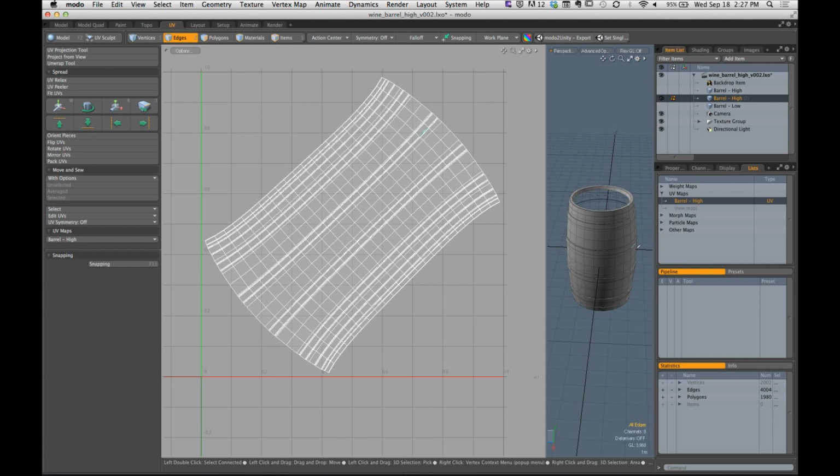In doing so, we're creating a little border for the computer, almost an extents. We're telling the computer that it doesn't need to evaluate this shape outside of this border, and it just seems to work better from time to time. Cylinder, let's choose the initial projection axis to be X, and it's still not liking what you've got going on.